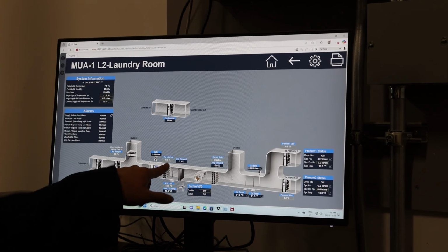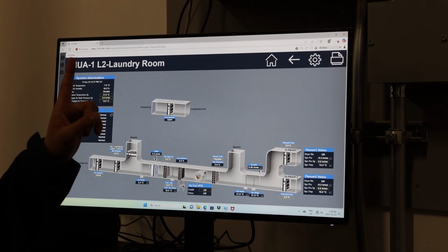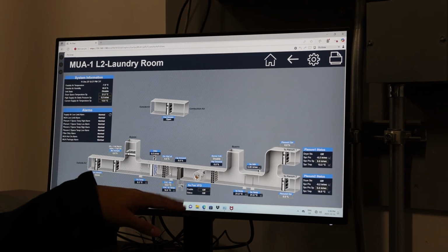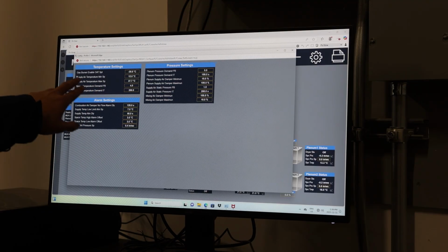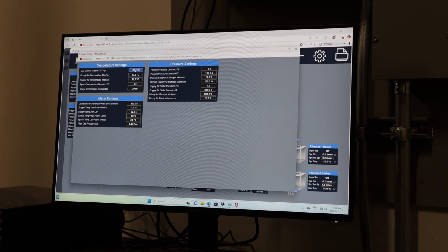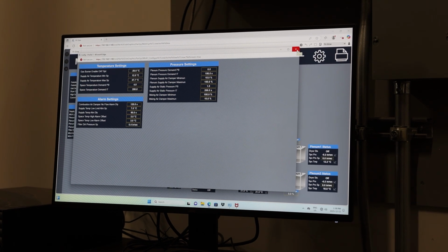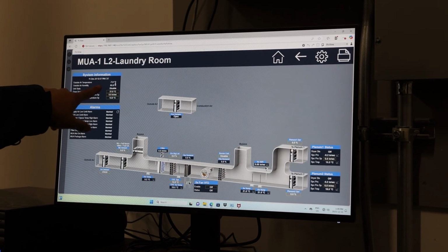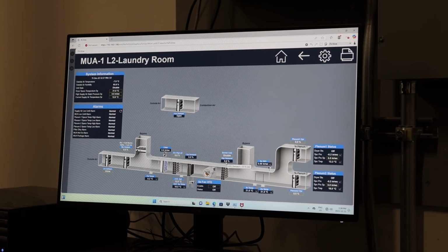Because we have electric heater and gas heater, we always want to use electric heater as a first stage. So most likely we always want to run this one instead of this one. So there is outside air temperature. Gas burner enable outside air temperature set point is -20. That means if the outside air temperature is above -20, let's say today is only -10, the gas burner is just disabled. There's no need.